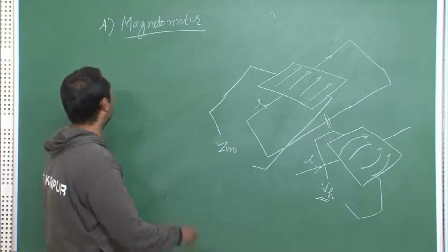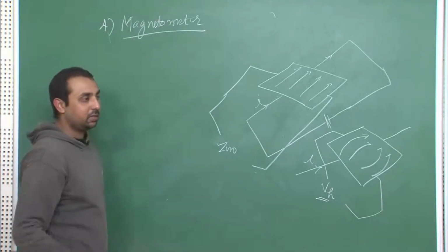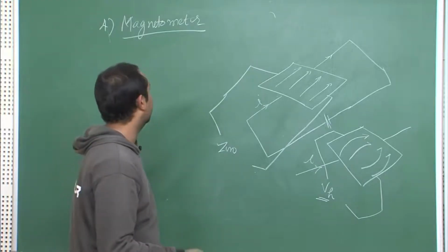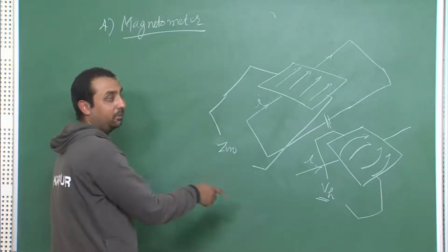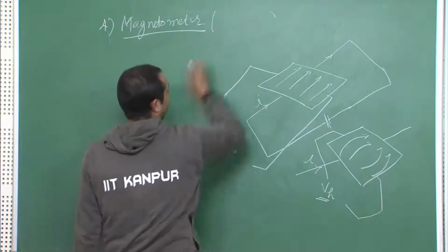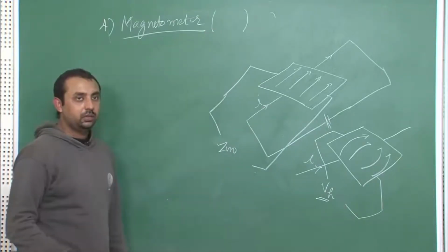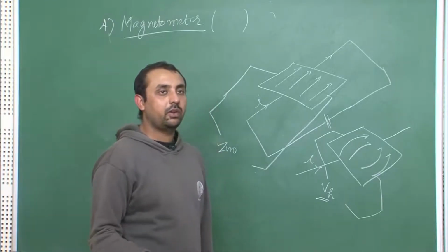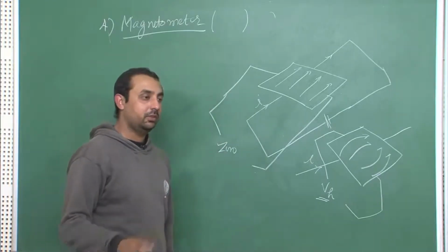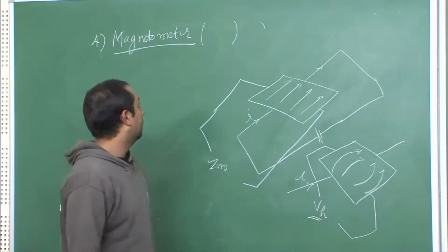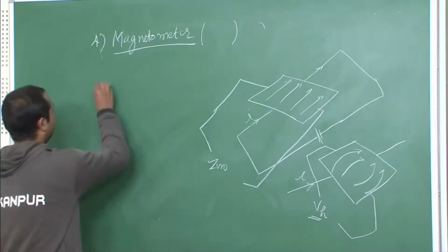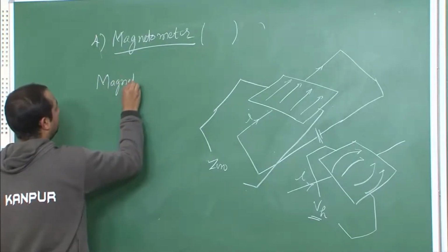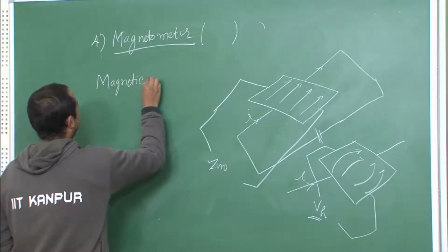Now your major magnetometer sensors which come in for your MEMS sensors, or for UAV applications, use this phenomenon or Hall effect for calculating your earth magnetic field. In UAV application, magnetometers are used to find your magnetic north, which is different from your actual north.